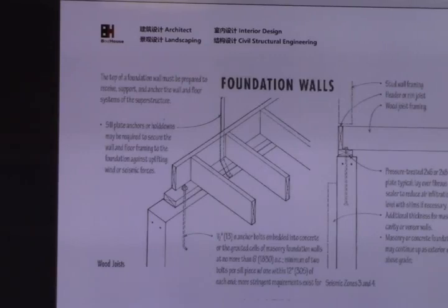It's something like a moment connection, right? We can see the moment connection here, because it's bent into the concrete. The concrete is very heavy, but the uplift from the wind is also heavy, so it also accepts the hold down.